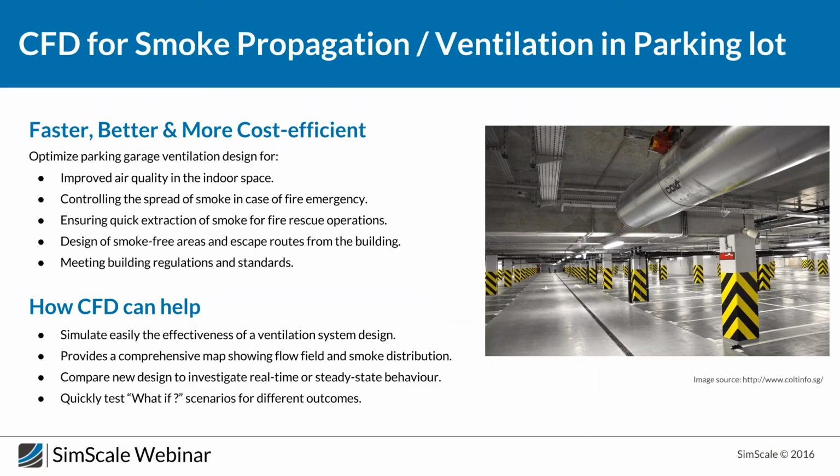At the same time, we could see in case something happens, in case there's a fire, how the front of the fire and the smoke propagate inside our domain. How long does it take for it to reach all parts of the garage? How long does it take for it to reach some risky levels after which nobody should be inside the garage? All of this could be addressed by CFD.